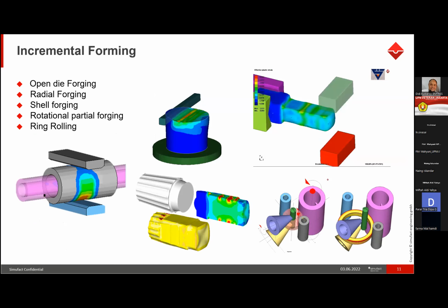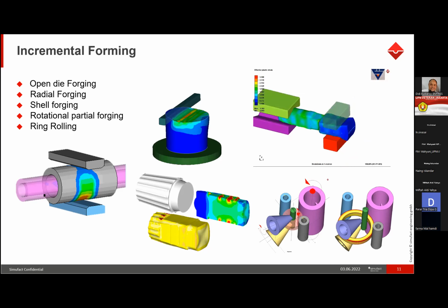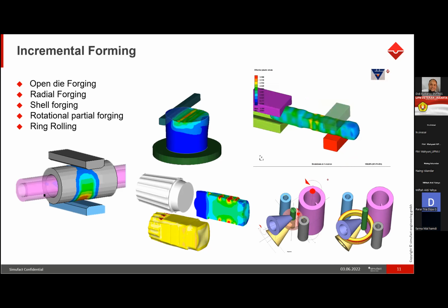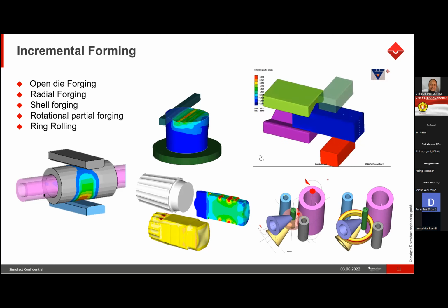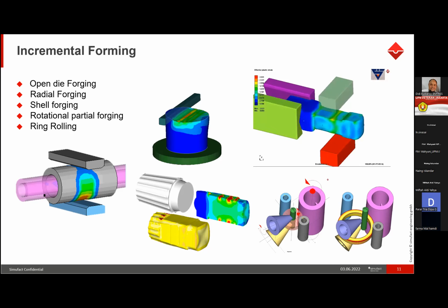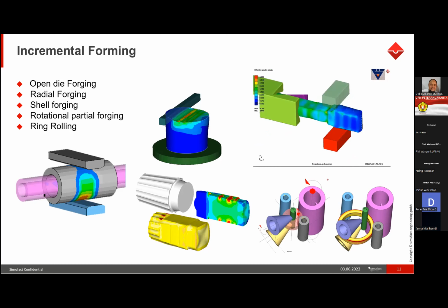So generally when any open die forging operation is being done, it is done through a hydraulic press or some kind of a hammer press where the motions are predefined. So with one set of inputs, the press automatically takes care of those inputs and then starts doing the deformation. The same way here also, you can give one line input and it can deform the whole thing in a sequential way that we want. So that we'll also be able to tell what will be the stages or what will be the dimension after the complete cogging operations.